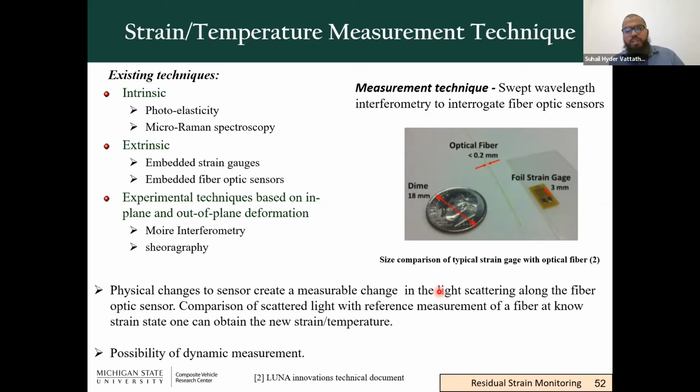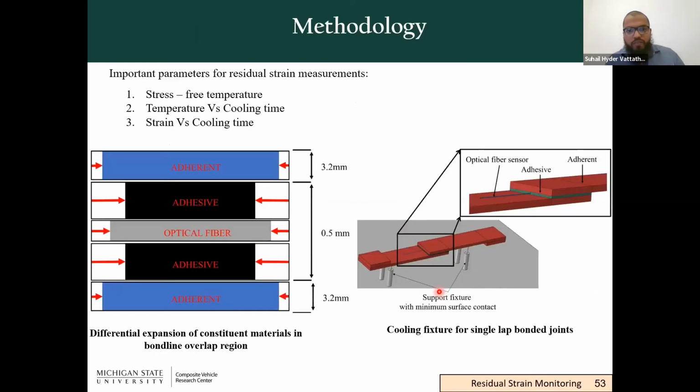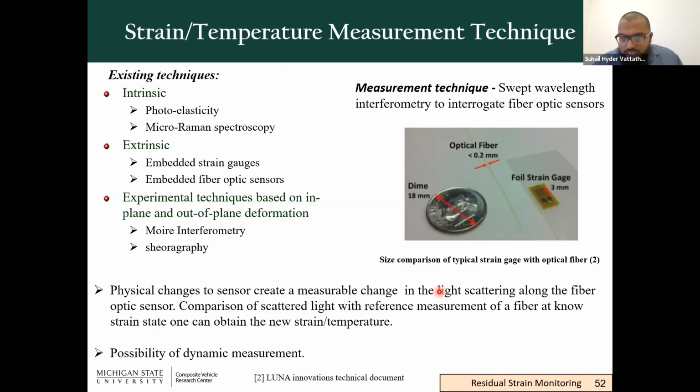So we thought of doing a combination of experimental and computational study to predict and monitor the residual stresses within the bonded joints. What we did was we used an optical fiber sensor, and the sensor is nearly 0.2 millimeters in size.